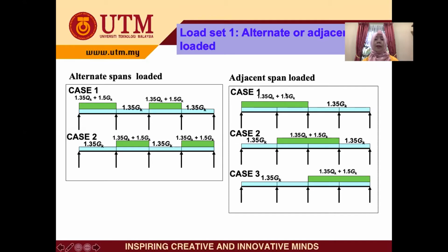Okay, for the adjacent span loaded, we have 3 cases as well. The adjacent span, that means span 1 and span 2, we apply the maximum load, and the other 2 spans minimum load. And then minimum, and both spans here maximum and minimum. Okay, so this is recommended by the Eurocode.